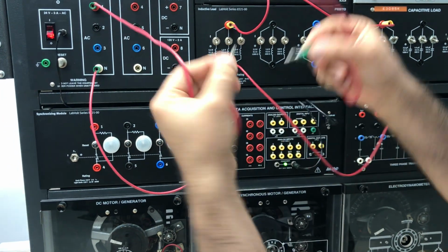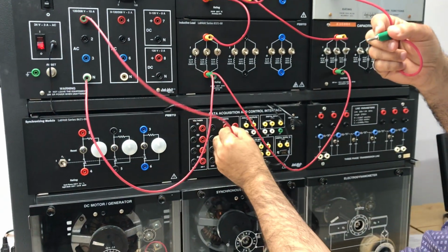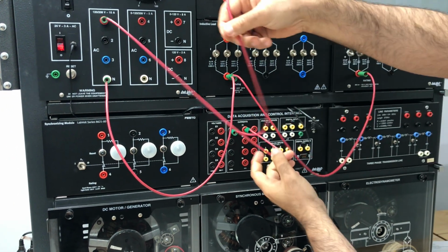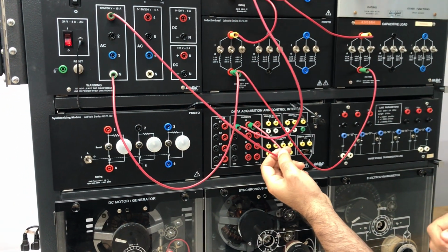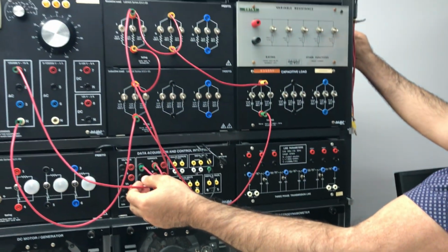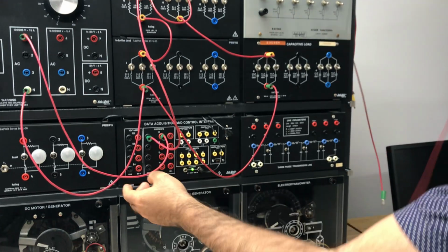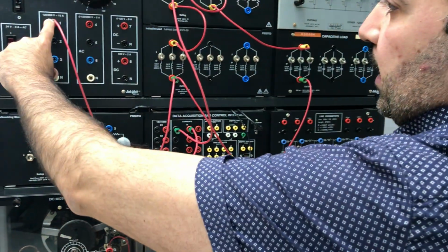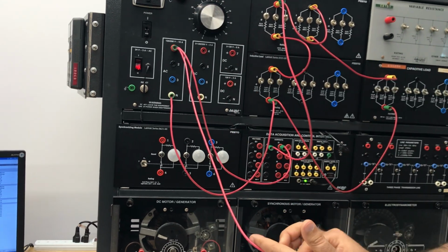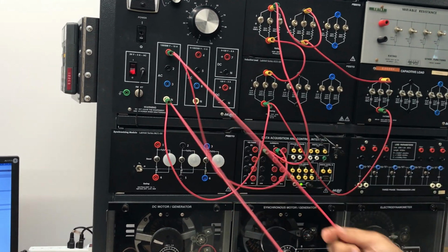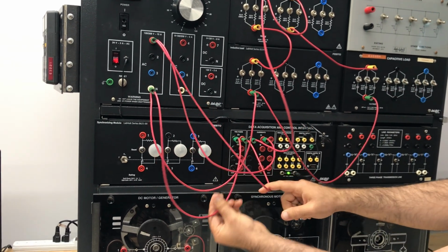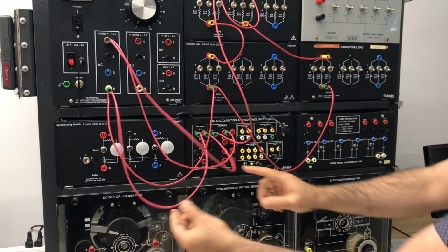So the current is going here from the supply to the meter, which is the ammeter, and then going from the ammeter to the resistive loads, or the capacitive or the inductive, based on what you are connecting to. Then I'm going to connect these two to the voltmeter in parallel. So this one and this one are going to be connected between this point and this point because I would like to measure the voltage.